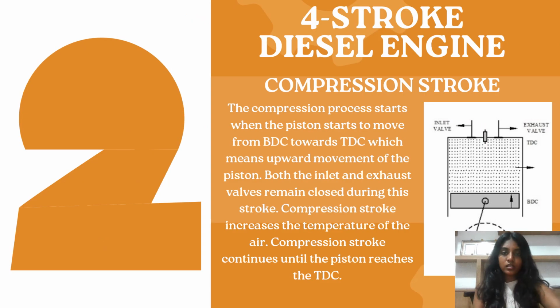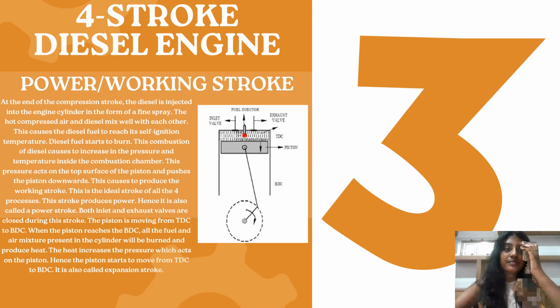Next, we have the compression stroke. The compression process starts when the piston starts to move from BDC towards TDC, which means the upward movement of the piston. Both the inlet and exhaust valves remain closed during this stroke. The compression stroke increases the temperature of the air and it continues until the piston reaches TDC.